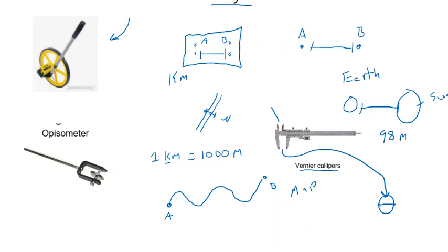Also, you have this side here, and this enables you to measure, let's say, a piece of copper pipe, something like this. Okay, and this is a piece of copper pipe and it's open. So what you want to do is get the distance between here and here, so measure that diameter. You can use this side of the vernier caliper to measure that as well.